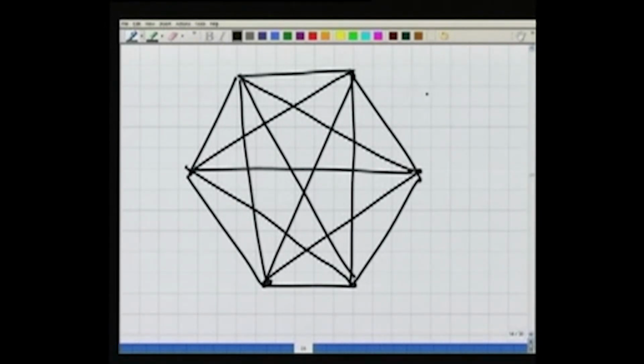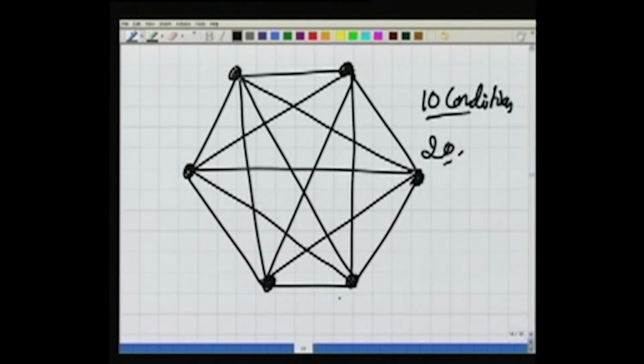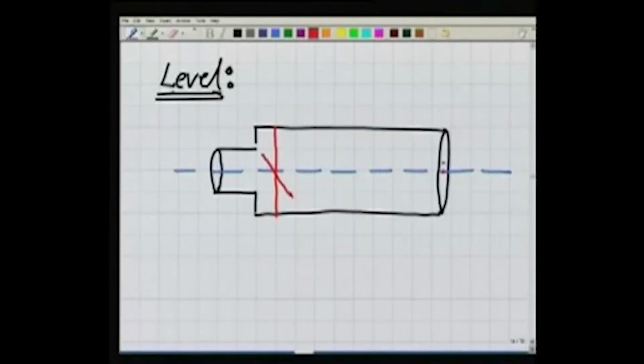And it has 10 conditions and 20 observations. So we will need to go for this kind of figure in order to have good geometric conditions in our trilateration figures. Well, having selected the figure we are going for, these are the ideal cases. Not always is this possible.